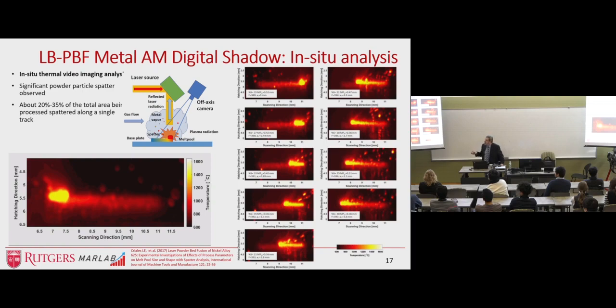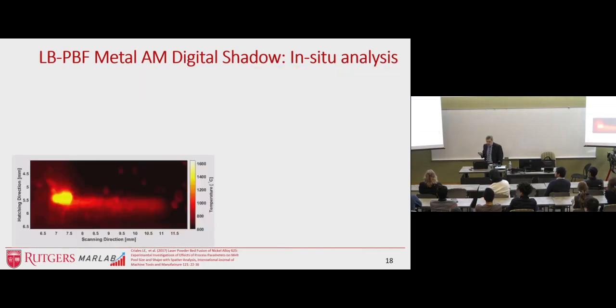Spatter is these particles flying from the melt pool. They are hot. Some of them actually evaporate, but some of them do not evaporate. They come back and stick to the surface and create surface roughness. So you do not want spatter to take place during the process. You can lower the density, you can lower the speed to avoid it, but that requires adaptive control, and it is not happening at the moment. Substantial powder material and heat loss takes place.